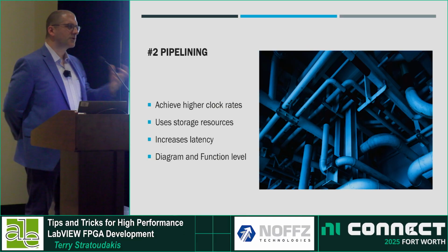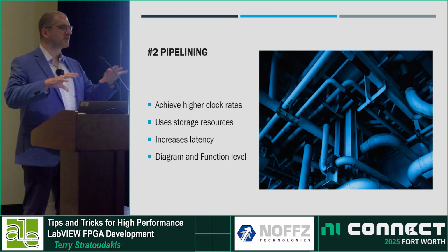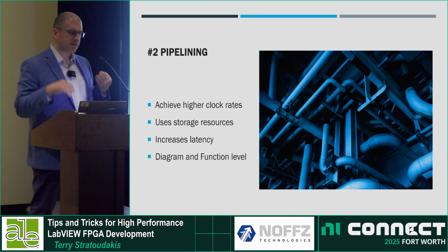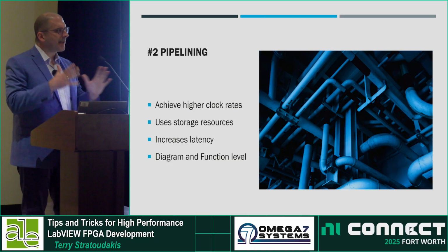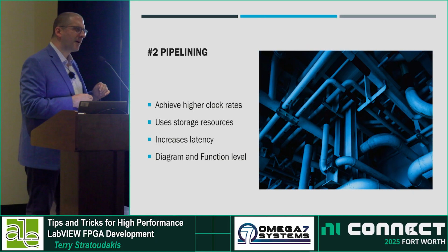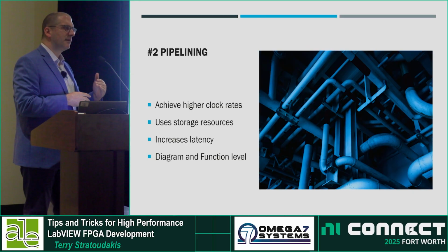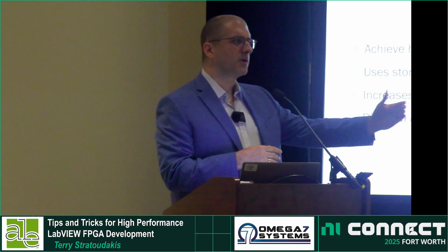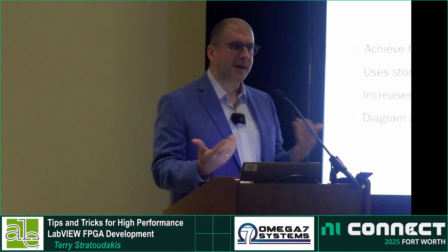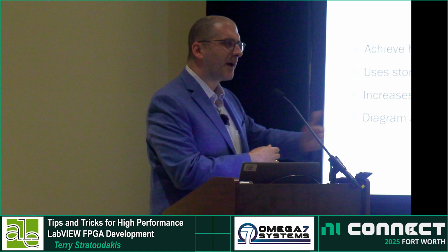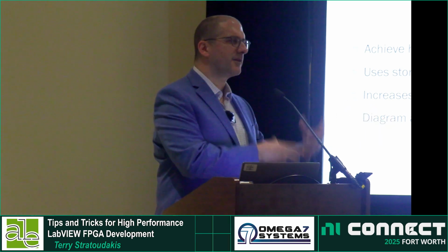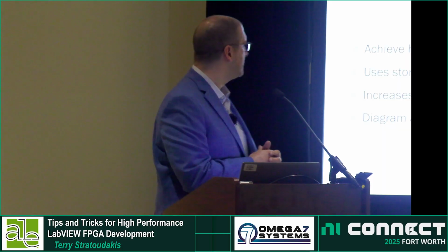It does use storage resources, so it will use either registers or, in LabVIEW, what look like shift registers, and that's how we achieve those higher clock rates. The other thing with pipelining is that it does add latency. More clock cycles to compute something is the cost of this. Again, it's a balancing act. You may keep adding pipelining to fit, but if the latency becomes too big, you may have to rework the algorithm itself.